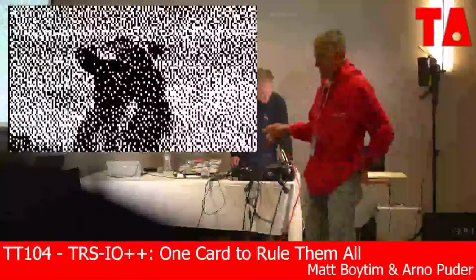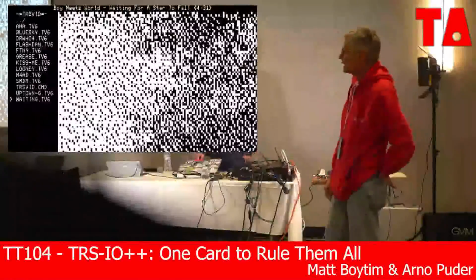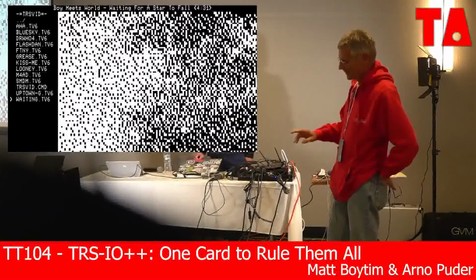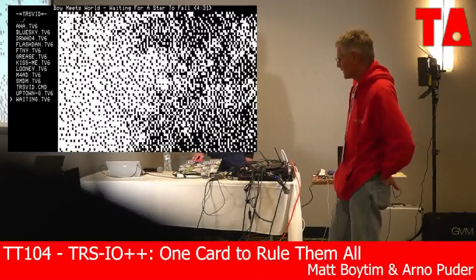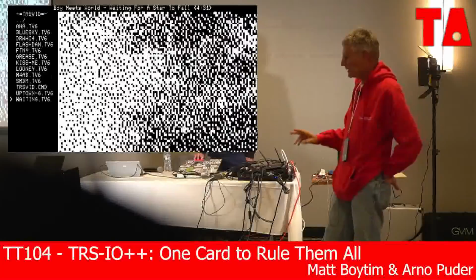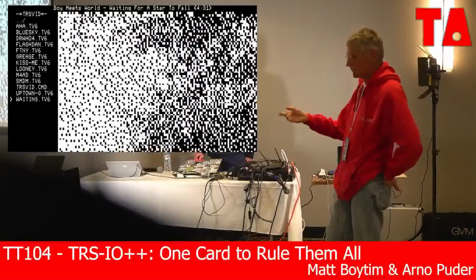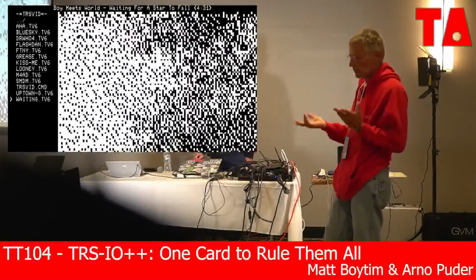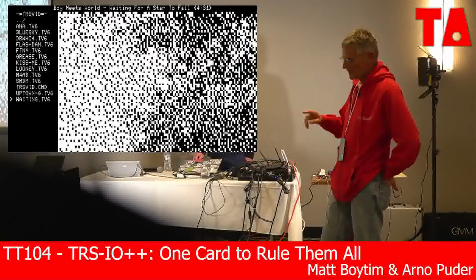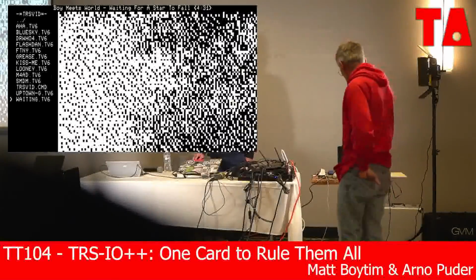So what I just did is, as I mentioned, the sound was one of the more interesting aspects of the design. The original implementation of sound sounded like that noisier version you just heard. Without going into a lot of detail, that was interesting because it was an unexpected result. It turns out the way that he generates the sound, he uses PWM, we resample that to go through the HDMI, and that resampling, if you're familiar with discrete time processing, results in aliasing. So what you're hearing is that aliasing. By filtering it prior to the resampling, you filter off all those components that would alias and generate that sound.